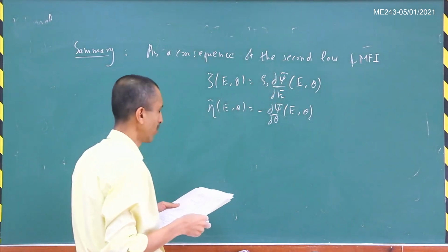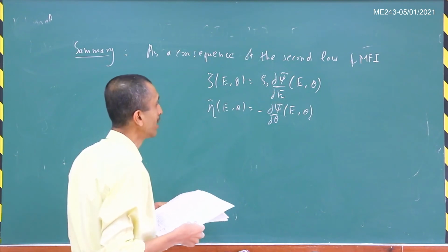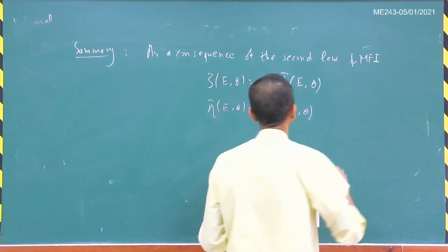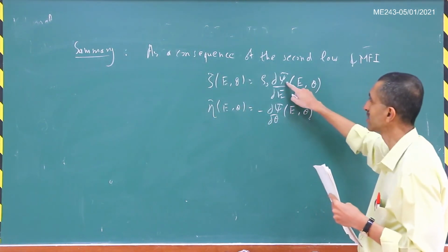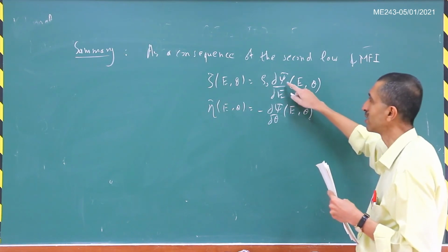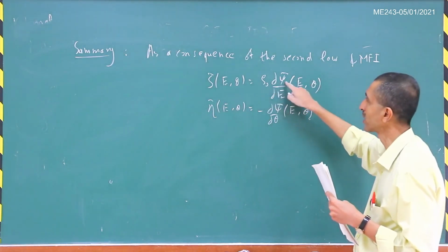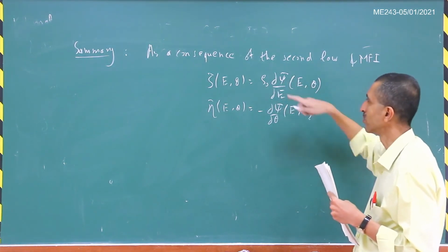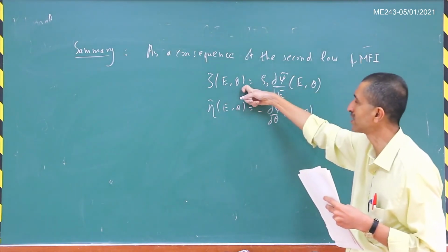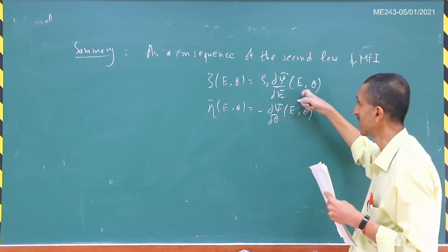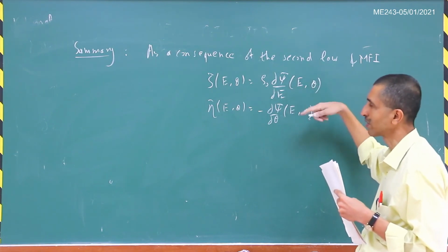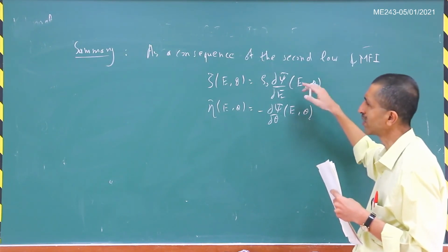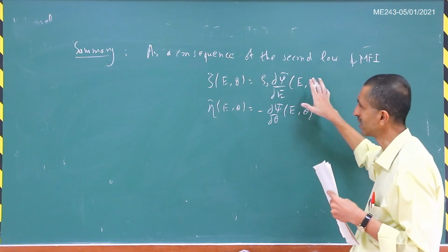And in fact, if we take the process to be isothermal, then in that particular case, you can take the theta to be a constant, right? And in that case, this will be exactly identical to the strain energy density. If I take rho naught times xi tilde to be the strain energy density function, then you will get the second Piola-Kirchhoff stress as a gradient of the strain energy density function if it is an isothermal process. Similarly, for an isentropic process also, we can show that there exists a strain energy density function. So basically, we will look at this aspect in greater detail in the next class.